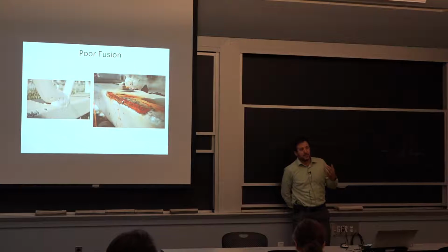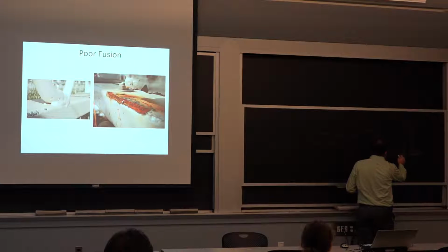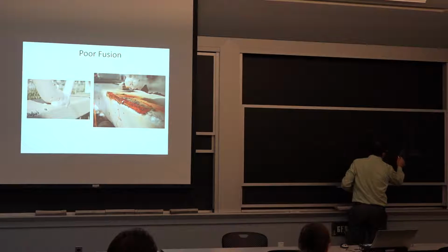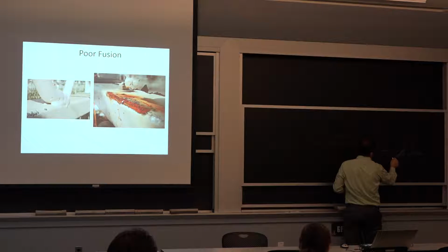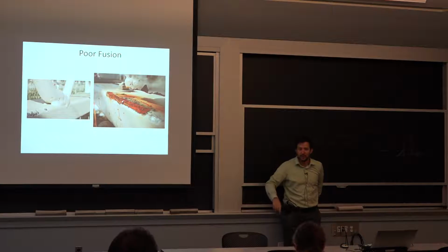And just so we all understand why that happens, is they're welding pretty thin material. So we're talking about something that's about just 1/8 of an inch, and they're putting a big weld on it because they know it's at the corner, so they want a lot of material. So if they were to make what I would call a good structural weld like this, a good one is going to have a little bit more of an angle. Let's put it almost straight for now. That's perfectly acceptable. If you were to do that, you get too much fusion into the material here. So if your thickness is only this way, it's called a burn through. That's not good, because now you have to go and fix it again.